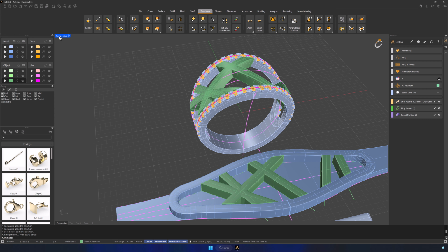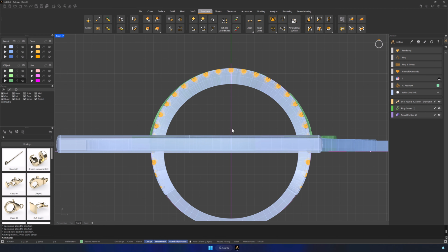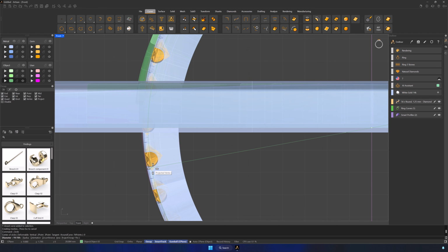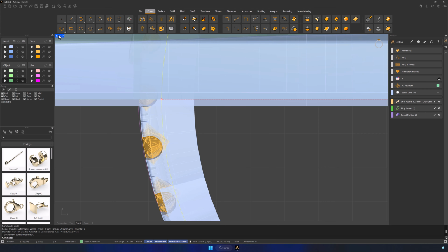Just a few details left to refine. Change the display mode of the front view to ghosted so you can better see inside the elements. Go to the Curve tab and create a circle. Set the center point to 0 and draw a circle large enough to slightly exceed the height of the gem's bottom point. Select the curve and switch back to the 4 viewports.